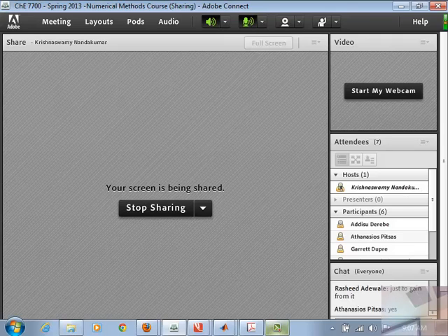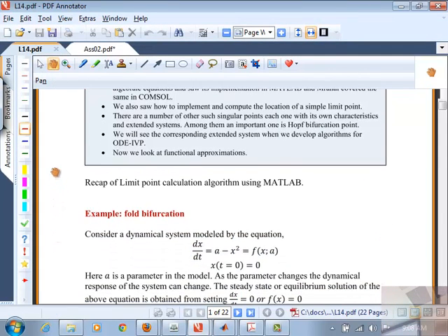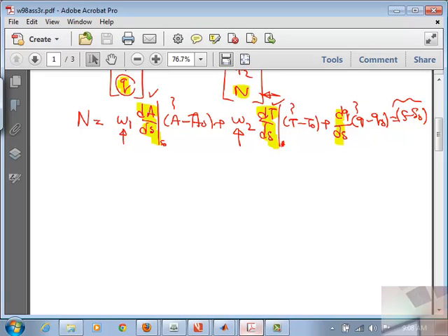Any other questions on the current assignment? I'm using the PDE coefficients form. Can I use that to build my equation? Which coefficient? The PDE in one dimension? You can use general PDE, or there is a similar structure of equation: the heat equation will have a second order term and Poisson's equation will have a second order term. So you could use any of those. You just want to make sure that the structure of this problem resembles that, and you can make appropriate coefficients.